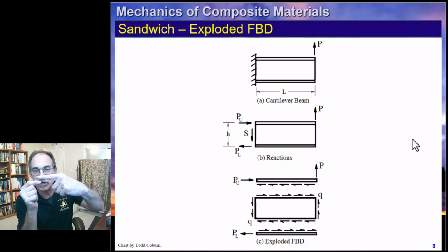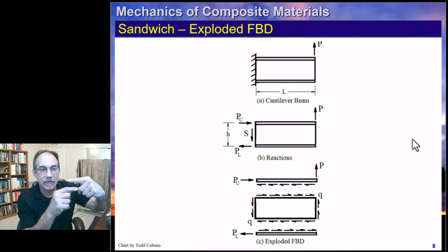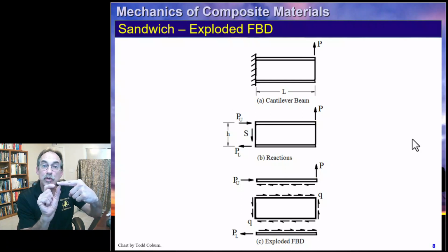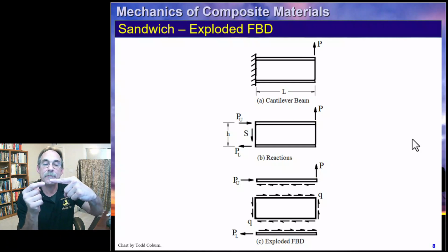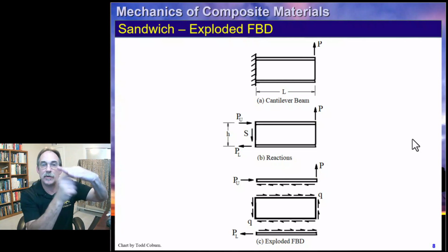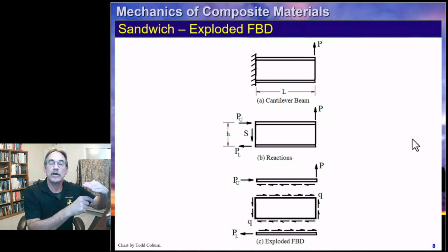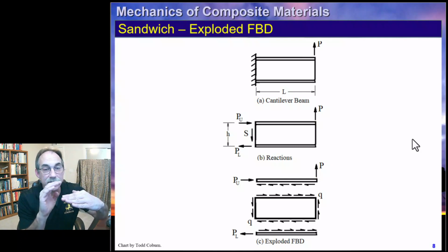And we have these little shear flows pushing it. So in 1 inch, it gets Q times 1, which is how much force is now on the facesheet. And the 2nd inch, Q times the 2nd inch gives another piece. So because of this action of the shear flow acting on the bottom of the facesheet, it's adding more and more force into the upper cap.